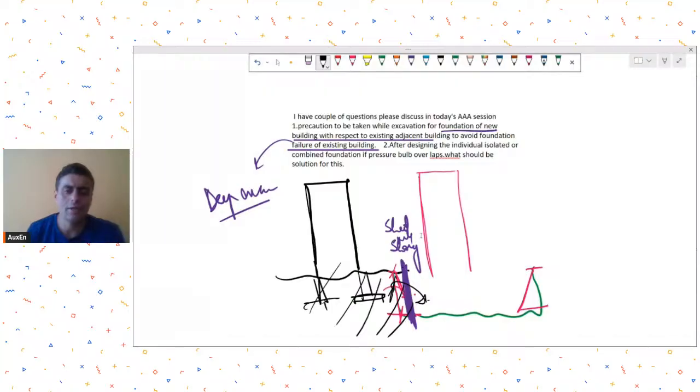If you had hard strata, maybe you will not be very worried about these things. But in strata where it is prone to collapse, where the soil cohesion is less, over there you may have to come up with these systems. Typically, you may also design these systems, but the guidance and requirement is generally given by the geotechnical engineers.